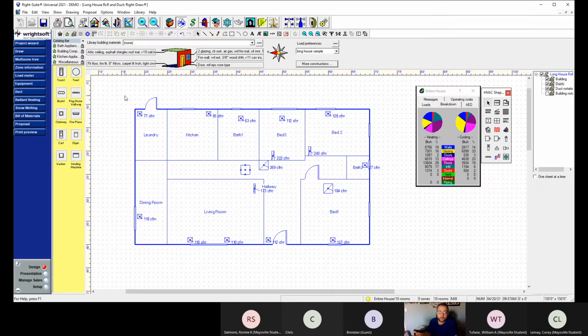And then, okay, what was our static? What was our friction rate? Our friction rate was this. Okay, so if we adjust it for our calculated friction rate, how does that change the size of our duct? So in order to do that, you have to know your total equivalent length, which would be handy if I could get this to draw, because it shows me all that.